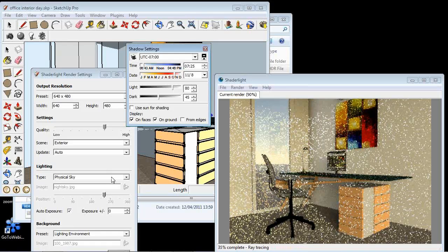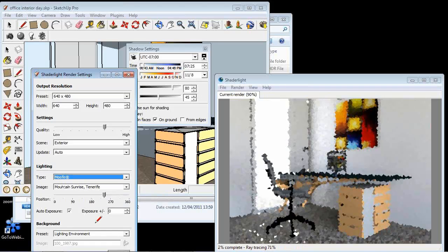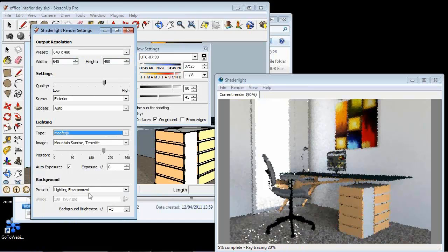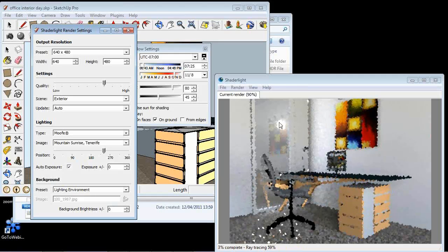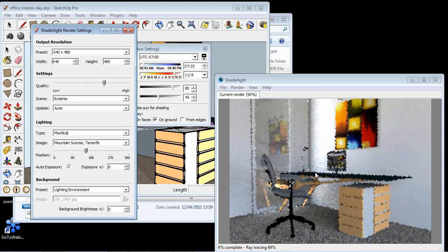Okay, so that's really what's going on with the image-based lighting. So those IBLs. If I move to one of our previews here, we go to mountain sunrise, we've got that very different lighting feel. I can turn down the background brightness there if you want to see that through the window. So it's combining those two. So there's the sun coming directly through there. So it's combining those two things, and you can really get the style that you want using all the different IBLs. So if there's any questions on IBLs, happy to answer those before we move into IES. But hopefully that's giving you an understanding of where and how you can use the image-based lighting.